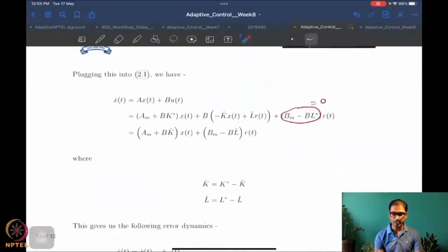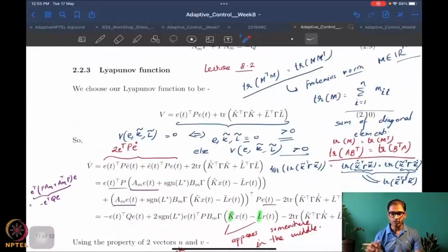And because we were dealing with matrix unknowns, we also learned a rather novel way of designing Lyapunov candidate functions for matrix states or matrix unknowns. So here the parameter error term, instead of just being a square of the vector norm, is in fact a weighted matrix Frobenius norm, and it is defined in terms of the trace function. So this was the big difference.